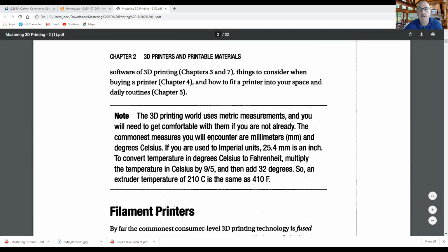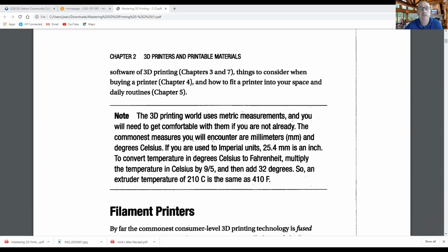So when we bring something into the slicing program, if I go here and say File Open, and I go into my 3D printing, here's a tag that we created, and I open it, it's tiny. And so that's because this was done in inches. And so what I'll do is I'll scale that by 2540. And so that's just an example of how the metric world kind of ties into our 3D printing.